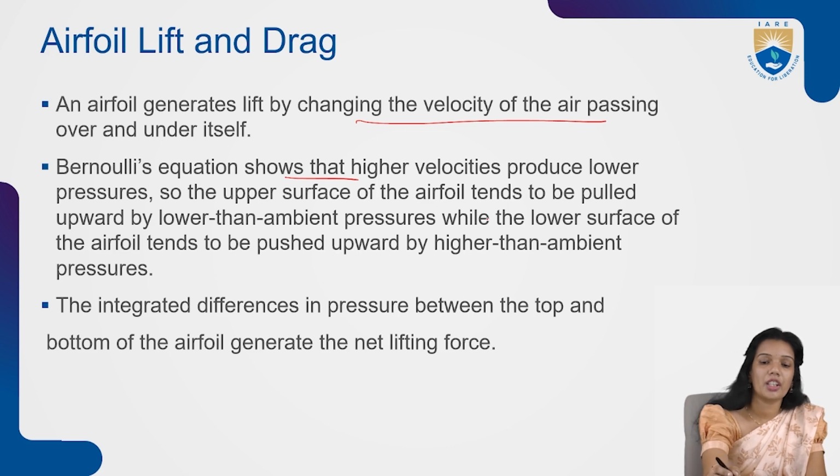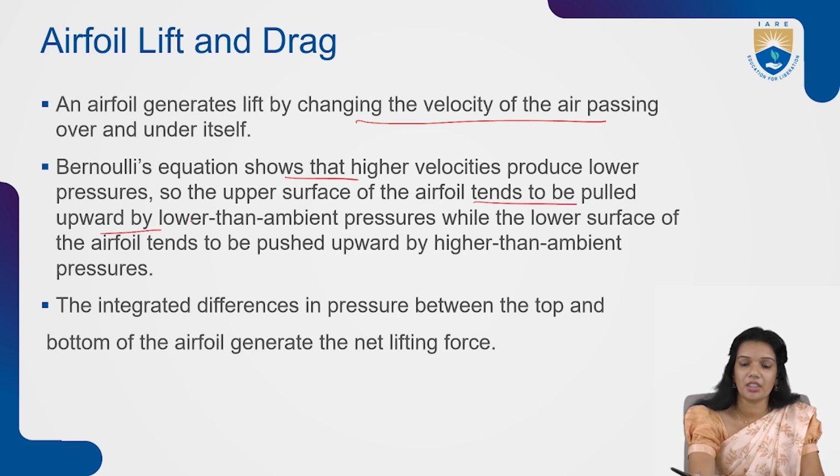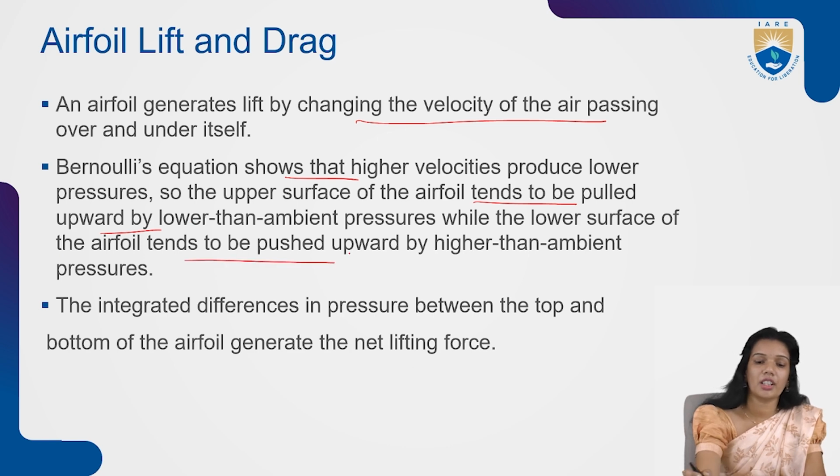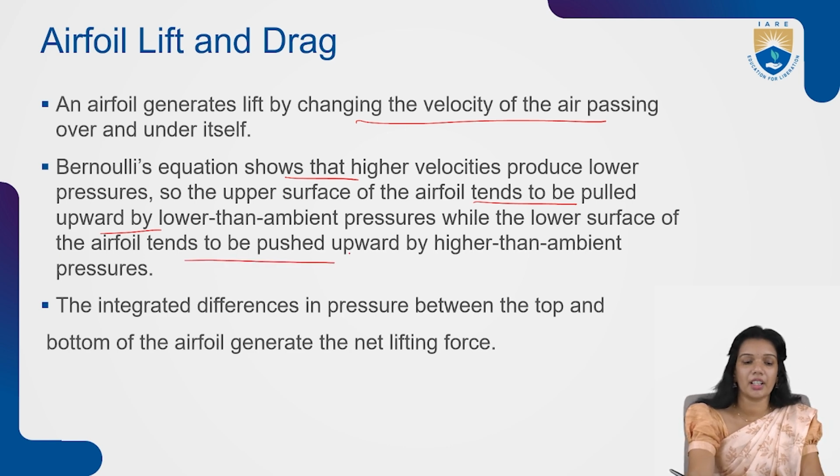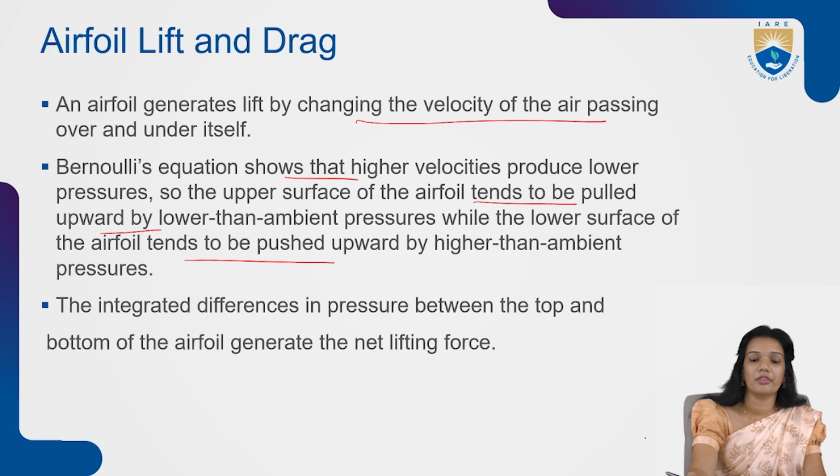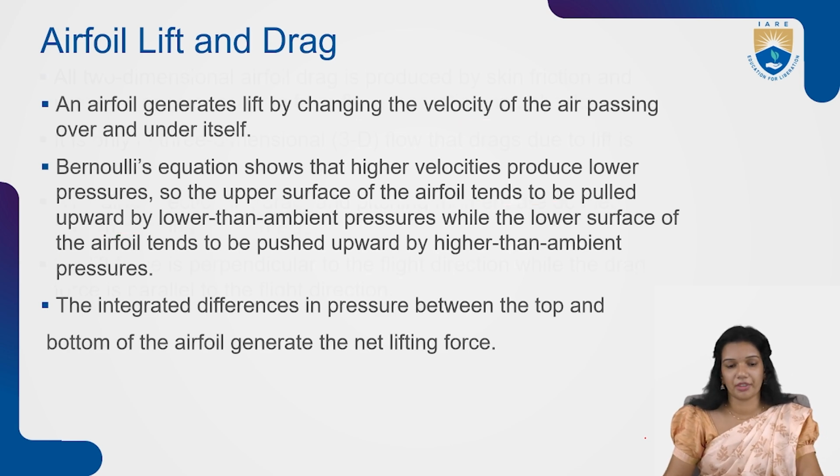So the upper surface of the airfoil tends to be pulled upward by lower than ambient pressure, while the lower surface of the airfoil tends to be pushed upward by higher than ambient pressure, right? The difference of it will generate the net amount of lift.